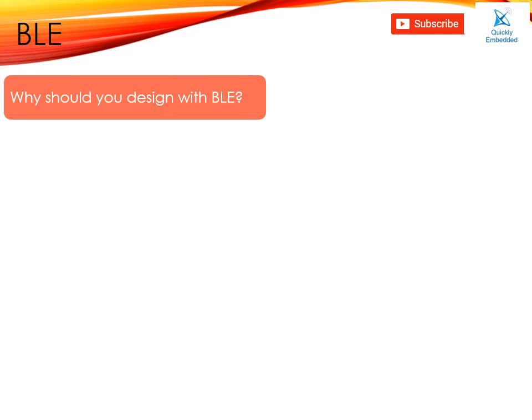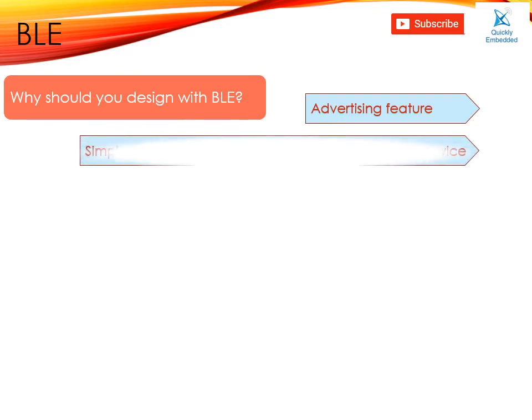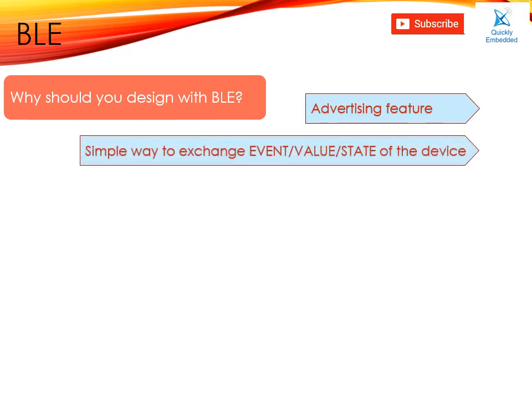Let's see why we should really design with BLE, right? So there are many reasons. A new feature BLE adds compared to classic Bluetooth technology is advertising functionality. With this feature, a device acting as a slave can announce that it has something to transmit to the master. An advertisement message can also include an event or a measurement value.